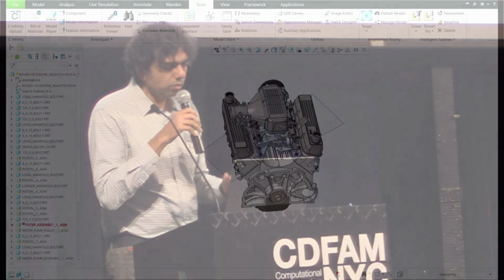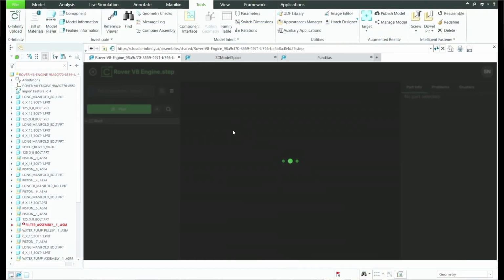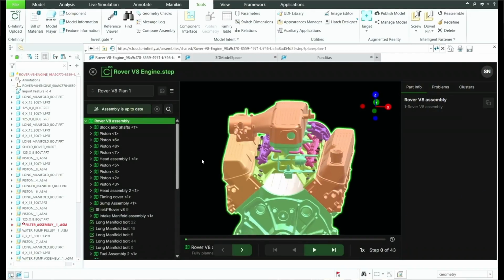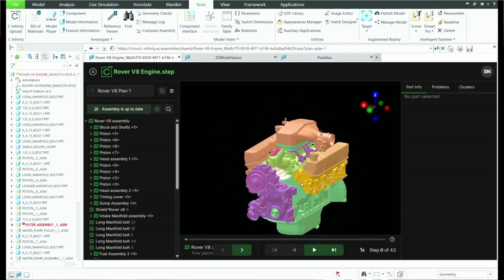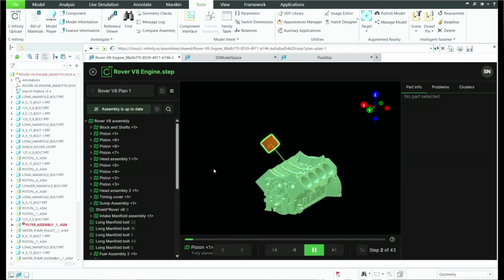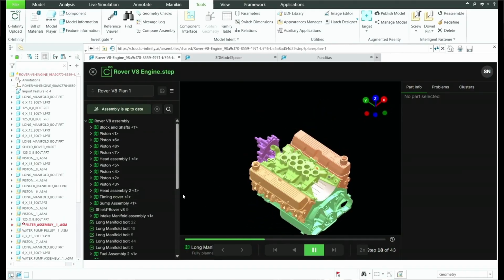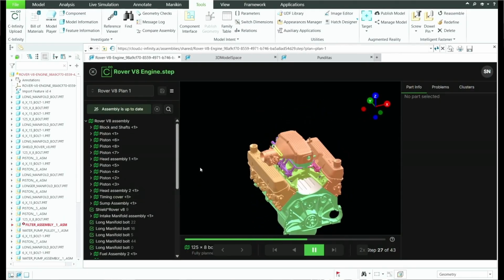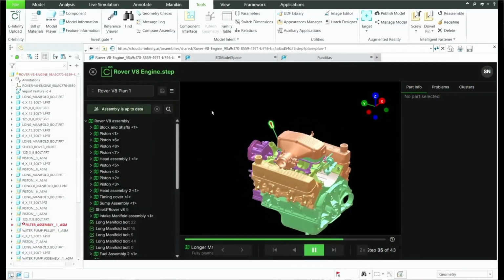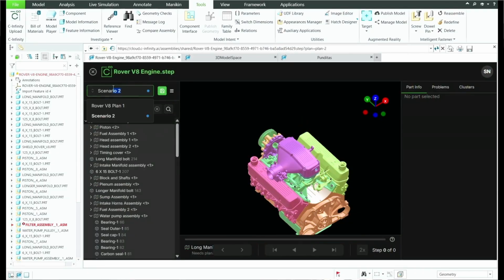So how does AutoAssembler work, right? It works inside your CAD program, and here I'm showing Creo, for example. And so what happens is you take your 3D model and you upload it into AutoAssembler inside your CAD program, and it comes up with an automated sequence of operations, like installation operations. It figures out the relationships between the part geometries, understands how they can be moved relative to each other, understands the precedence relationship of what needs to come before what, and organizes all of that into a coherent process plan.